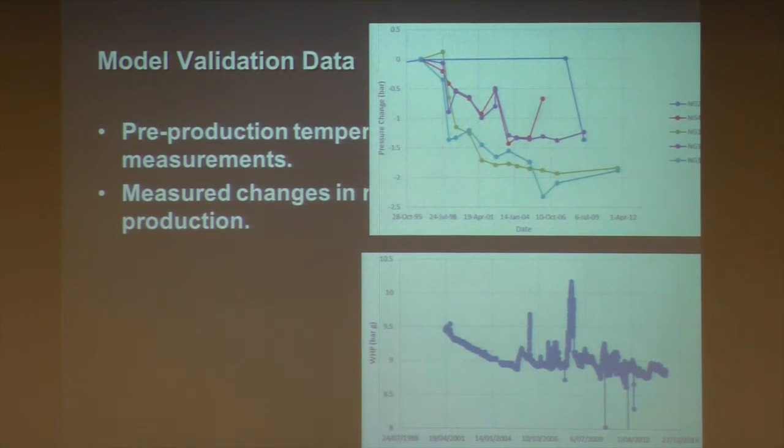So now we're injecting colder fluid into part of the reservoir. As that fluid is colder, it's denser, so it occupies a smaller volume, and that means that the fluid in the rest of the reservoir needs to expand to fill that volume, which slightly lowers the pressure. This is an effect that I think we have in all our producing reservoirs, but because the pressure changes are much higher in most reservoirs, you don't tend to notice that thermal effect, but it is important here in Ngawha.